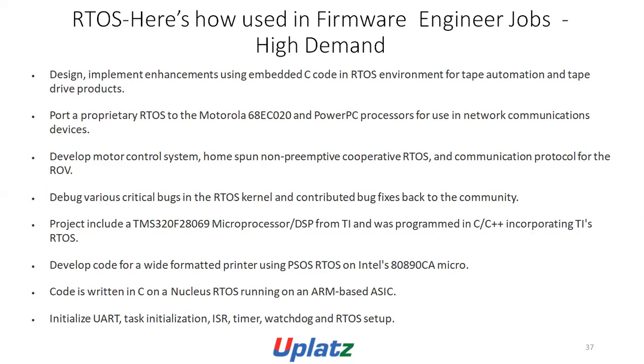Develop motor control systems, homespun, non-preemptive cooperative RTOS and communication protocols for the ROV. Debug various critical bugs in the RTOS kernel and contribute bug fixes back to the community. Project include TMS320F28069 microprocessor and DSP from TI and was programmed in C++ incorporating TI RTOS.